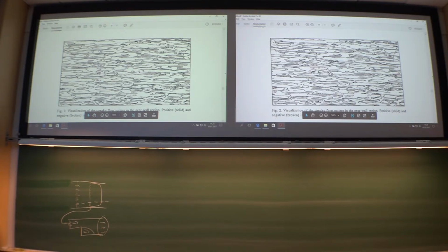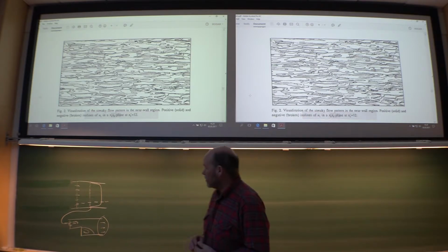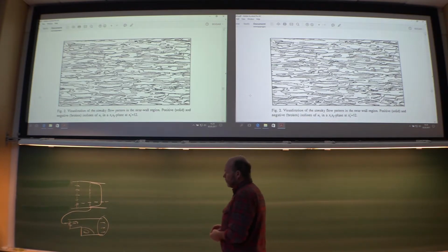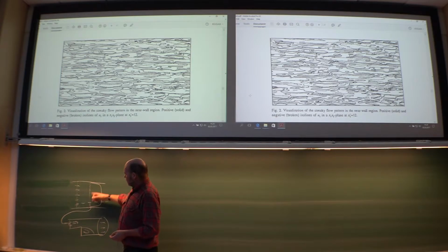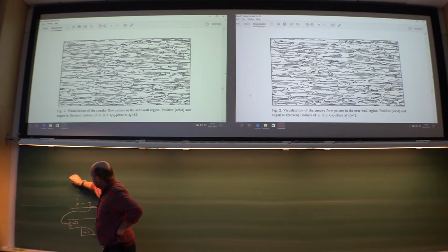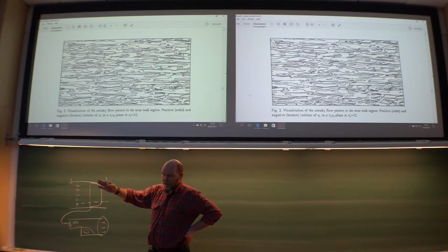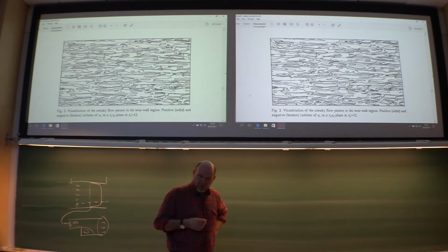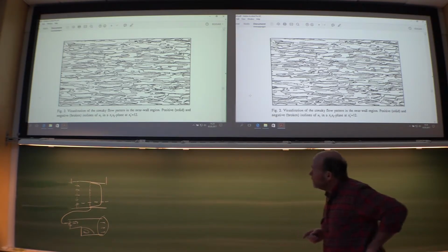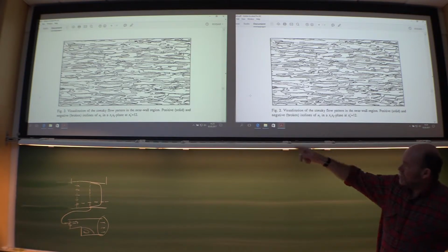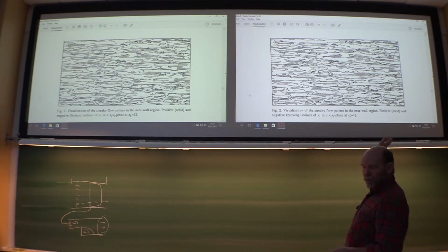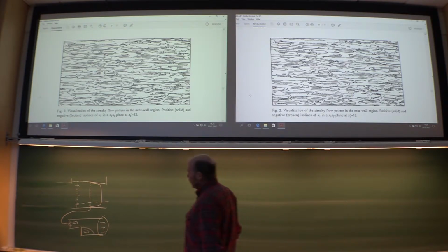This streaky structure that the turbulence has, that's also something you now have to pay attention to when you define your area. I mean, the distance from wall to wall, that's of course something you choose, but then you need to choose a length and then even a width in the z direction as well. How big should they be? Well, they have to be so big that these elongated structures don't go straight through the entire domain because of the cyclic boundary conditions.